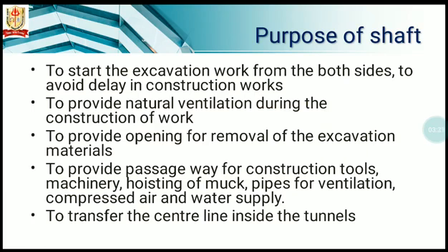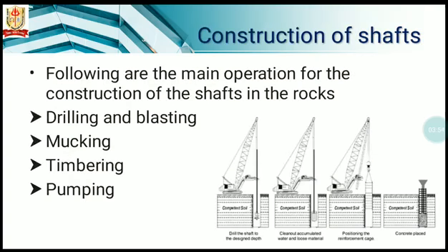Purpose of the shaft: to start the excavation from both sides to avoid delay in the construction, to provide natural ventilation during the construction work, to provide an opening for removal of excavated material, to provide a passageway for construction tools and machinery, posting of muck, pipes for ventilation, compressed air and water supply, and to transfer the center line inside the tunnel.